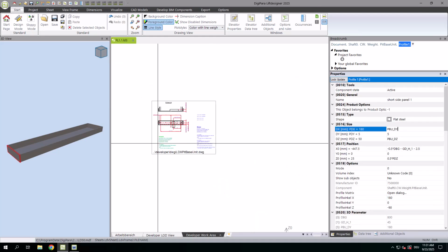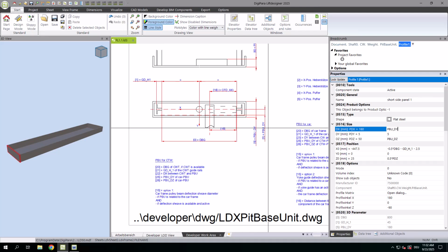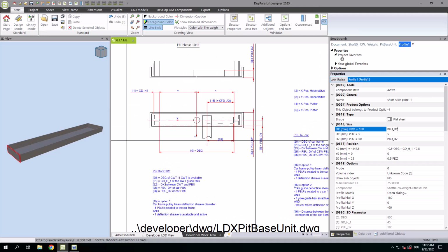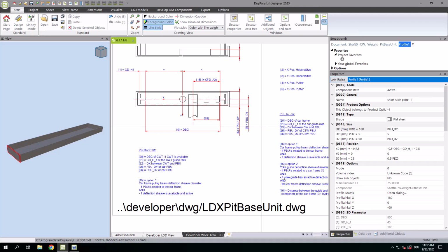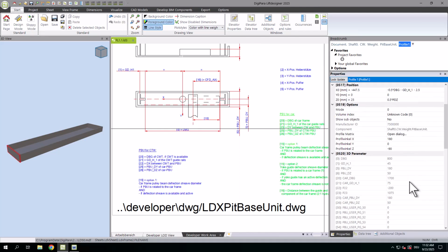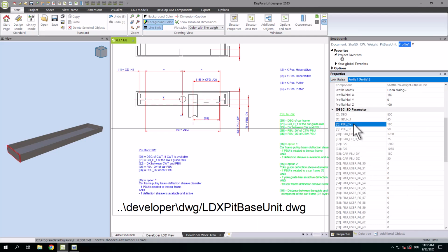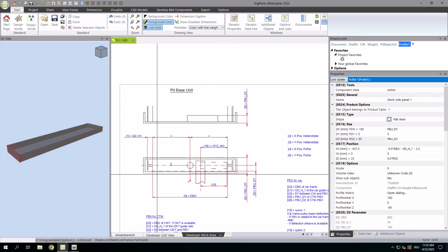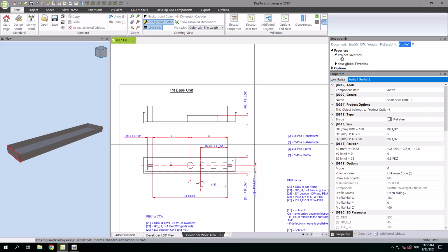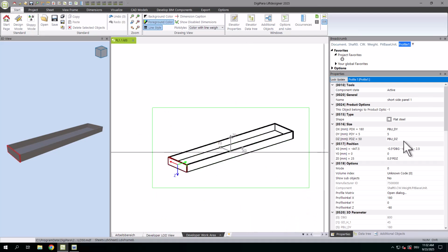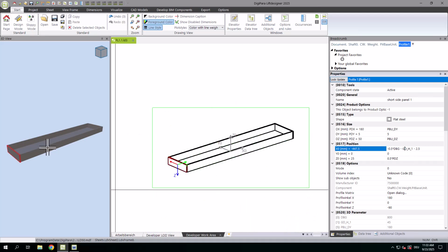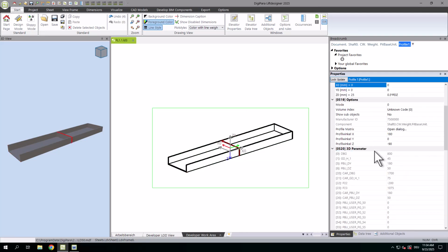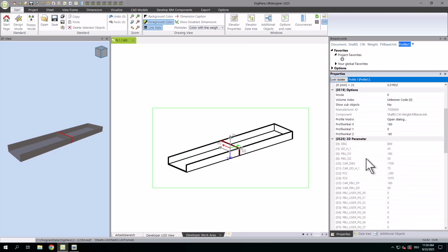For the size, you can rely on the loaded explanations of parameters and values in the developer work area. In this example, enter for dx the parameter PBU_dy. For dy, enter the value 5 mm, and for dz, enter the parameter PBU_dz. To position the profile, it helps to set the value to 0 to learn what the parameters are for.